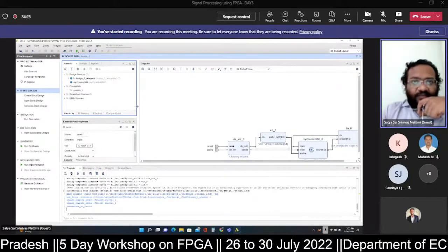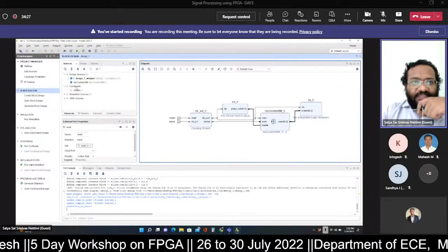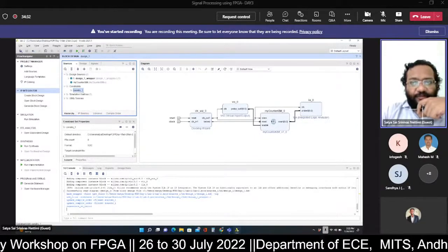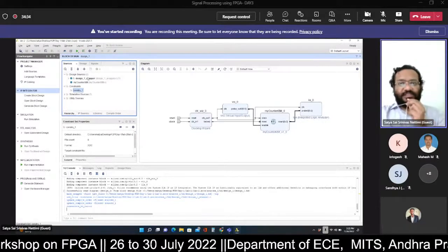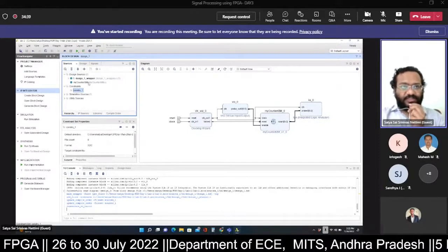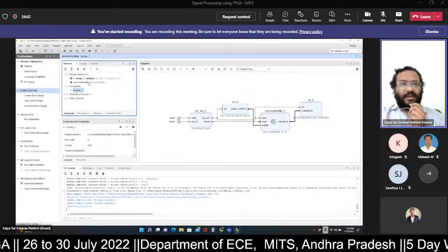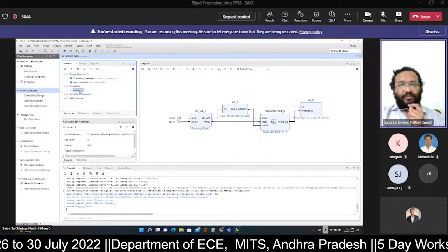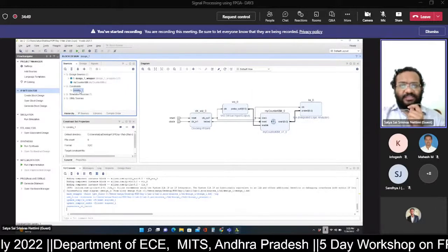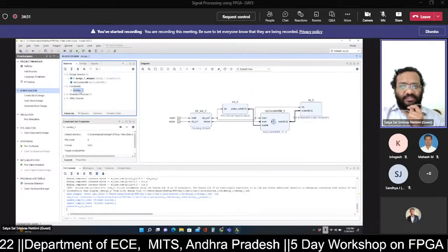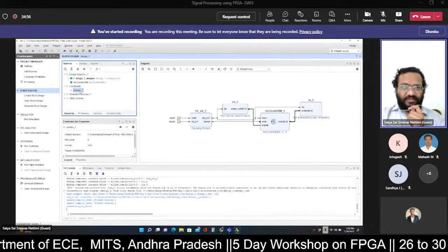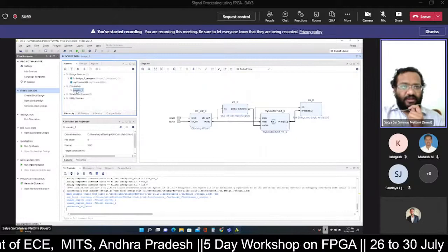First check whether any constraints file is already available in the project directory or not. Why? Because you can have any number of Verilog sources in the design sources folder, but within the project you need to maintain only one constraints file. If you already have a constraints file, then don't create a new one; just define all your constraints in that file itself. In my case, I don't have any constraints.